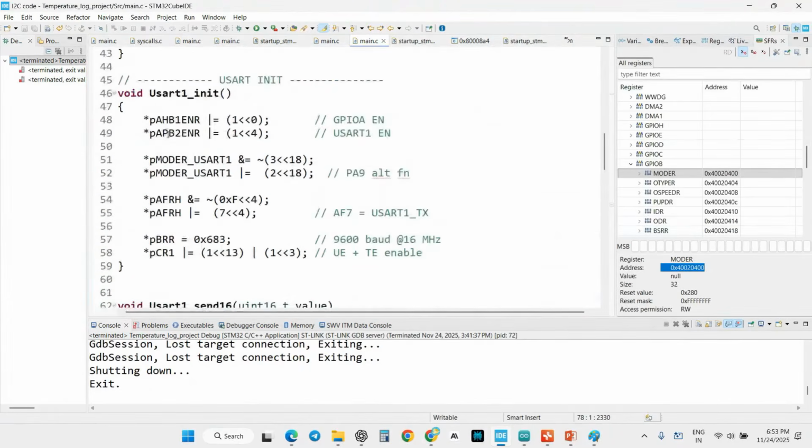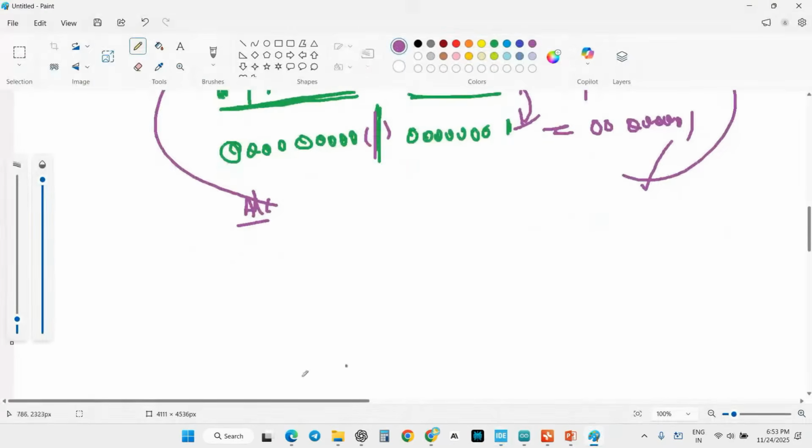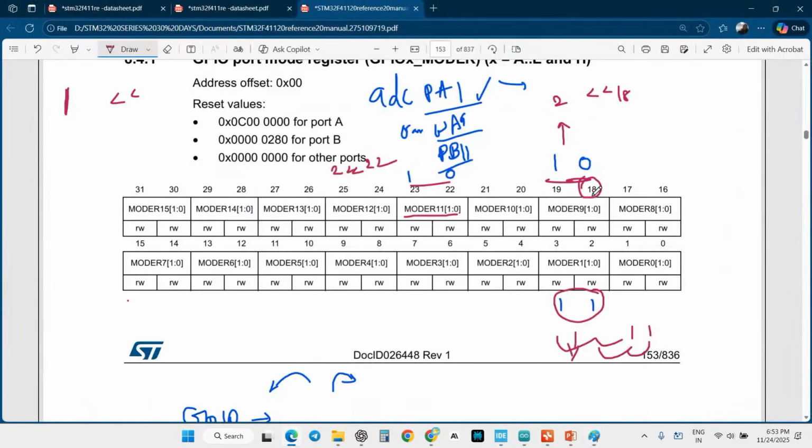So you might be asking this question: why do we have to use this UART 1 for resetting these bits? The resetting condition is that it has 2 bits, and some bits might already be configured. I have to clear these. We use the AND operator together with the NOT operation. So to clear a bit, you have to use these two operators to clear out the bits.